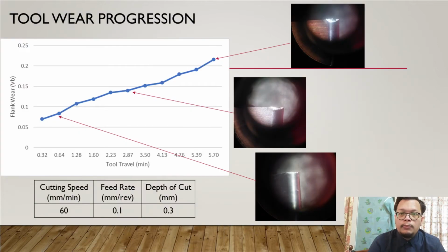For the tool wear progression part, tool wear commonly occurs in metal cutting, and in this experiment the coated carbide tool wear progression was recorded using the toolmaker microscope. The tool life of the cutting tool influenced the tool wear progression because longer tool life brings gradual wear progression.